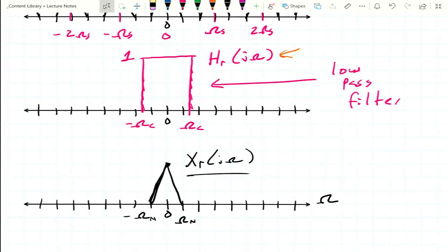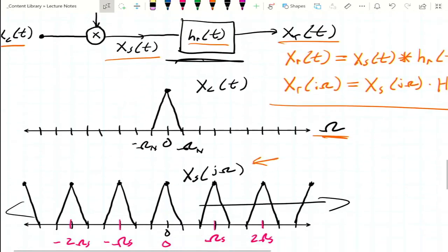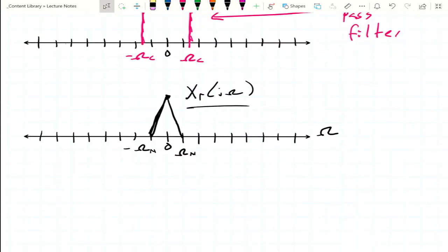So to kind of recap that, going back up to our, well, I'll leave that down here. Our original process is we take our signal, we multiply it by our sample function, and that's going to create that train of our original signal sort of connected to the impulse train, and then we're going to hit it with that low pass filter to get back just the original signal that we had. So this is the guy that's going to become our x sub n eventually, right? So we managed to recover that original signal.